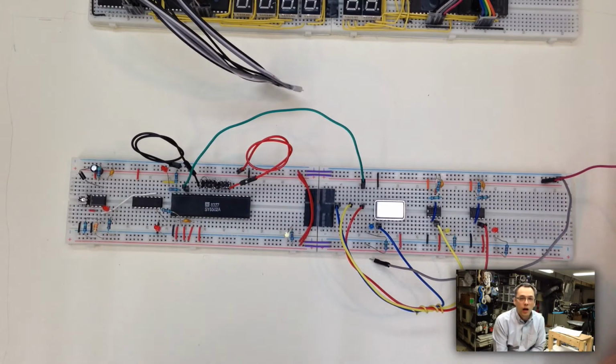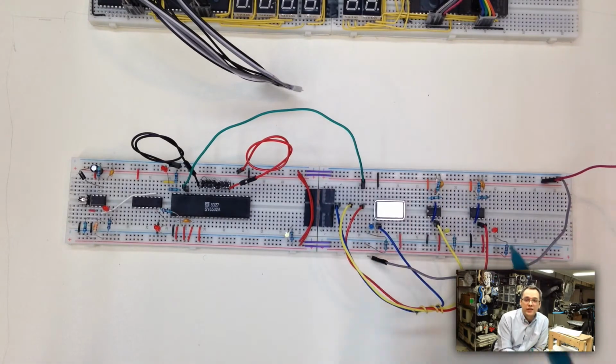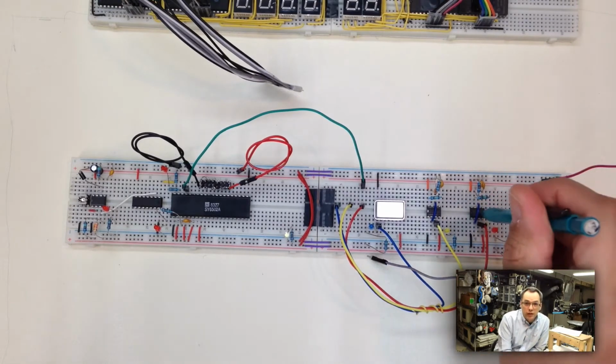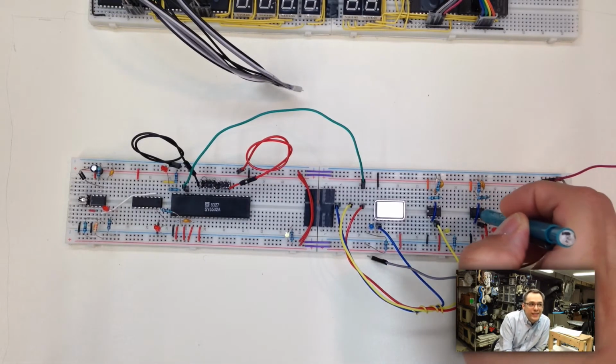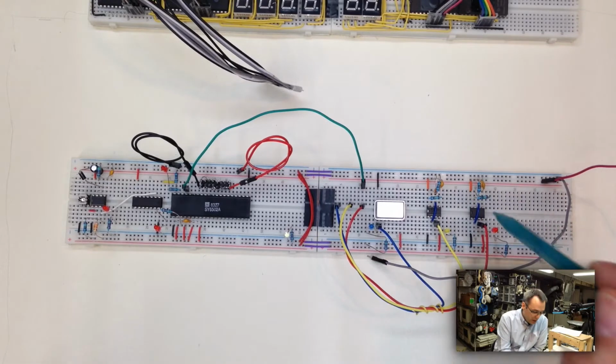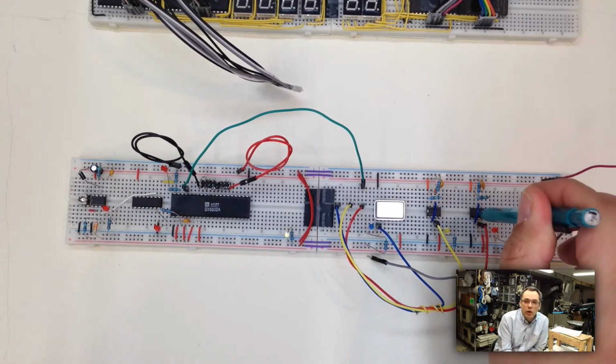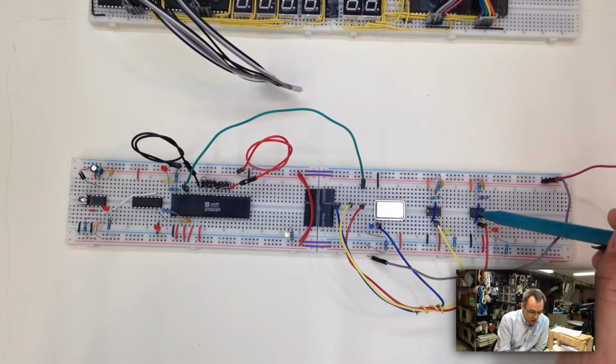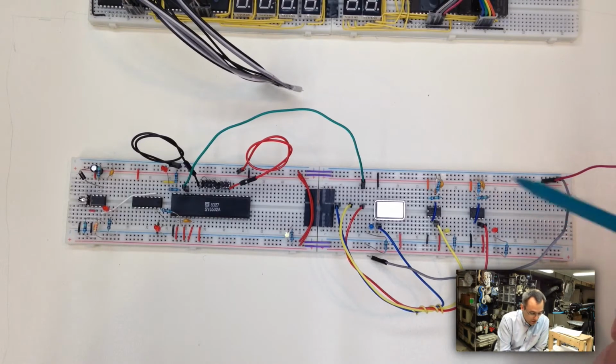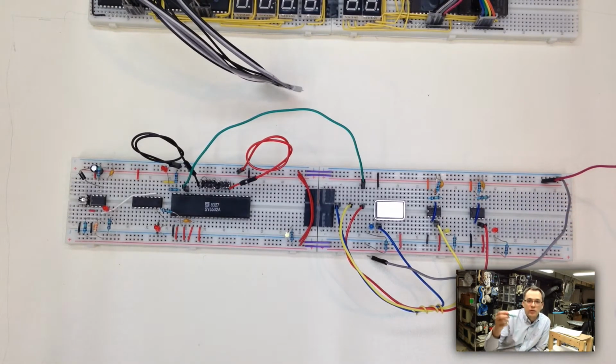Oscillator bank. I set up 3 different oscillators on this so I can run the machine at various different speeds to help me in diagnosing things. This oscillator right over here is our super slow oscillator. This oscillates at about 1.6 hertz or so. This is a 555 in astable mode, which means it works in conjunction with this capacitor resistor circuit, those guys right there, to cycle back and forth, on, off, on, off, over and over again.